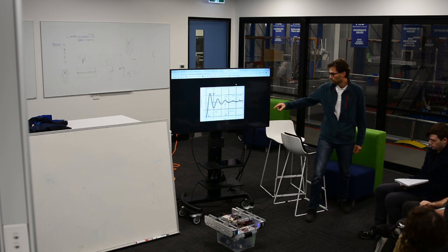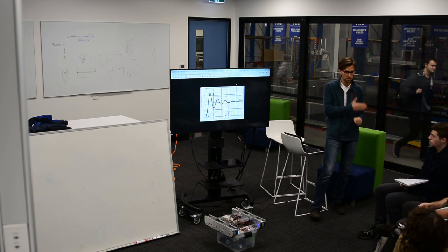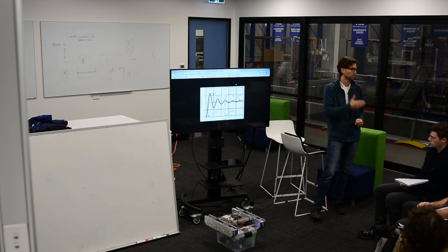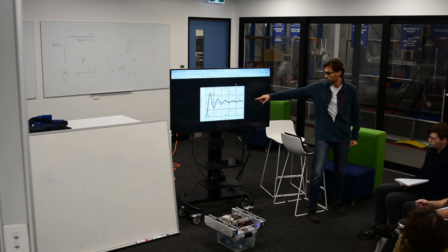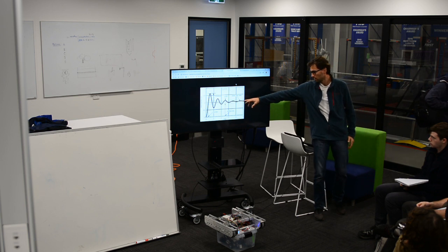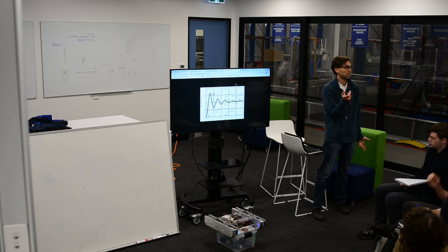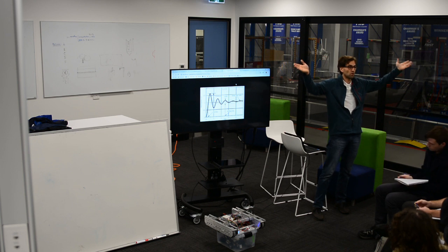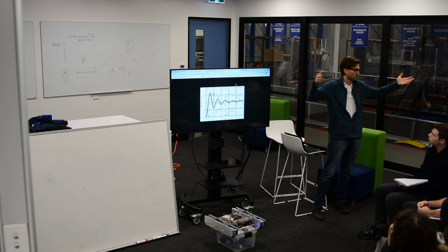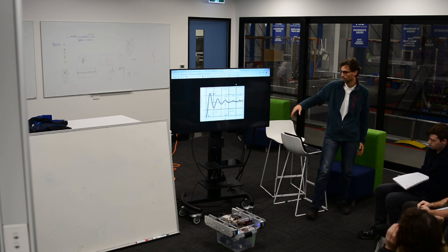We're trying to get that as small as we can, or within some band. Usually we characterize things by a step response: what happens if we try to immediately go from A to B, from 18 to 21? After some time, our system will settle, and we call that our steady state error value. If we try to move these wheels by one rotation, and our system moves them by 0.95 of a rotation and stops, and the control system goes, I'm done. No, control systems will never get exactly there. They're always going to get within some band. So there's this concept of a steady state error or a steady state value.